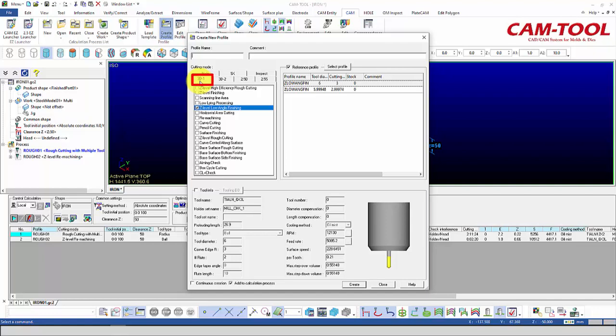For our semi program, we are going to use a Z-level low angle finishing located under the 3D1 tab. This type of program is designed to do both a Z-level finish for steeper areas and a scan or low-lying processing to handle the shallow areas. We will name this program Semi-01.